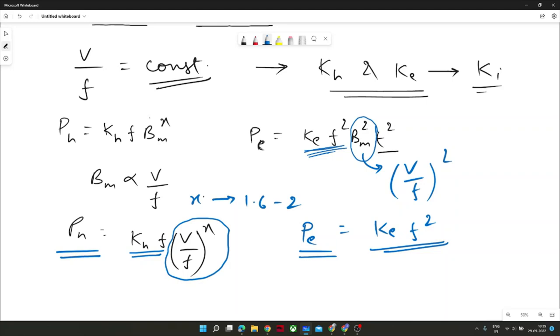So that's why we use lamination. Any motor would be laminated, the stack gets laminated. For that purpose, your eddy current losses depend on thickness T square. Why? Because the smaller the lamination thickness, the lesser the eddy current loss.